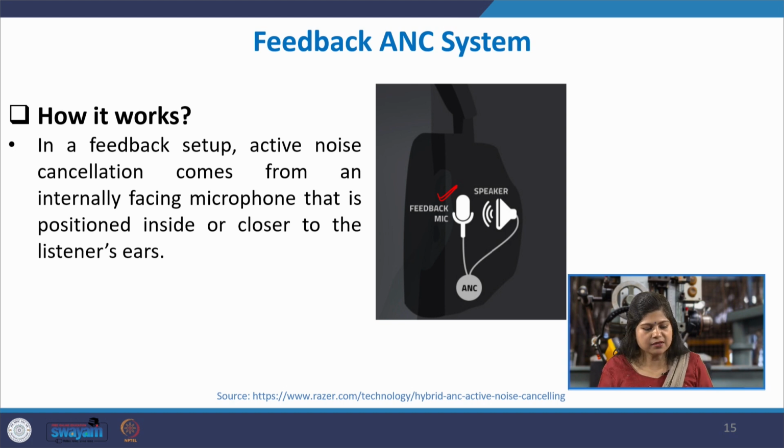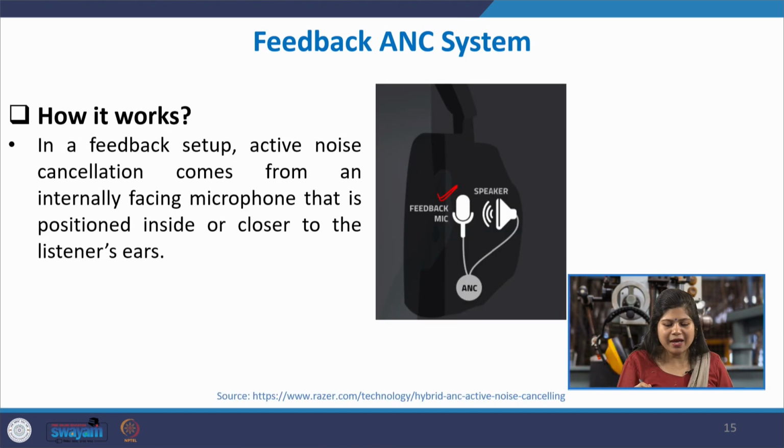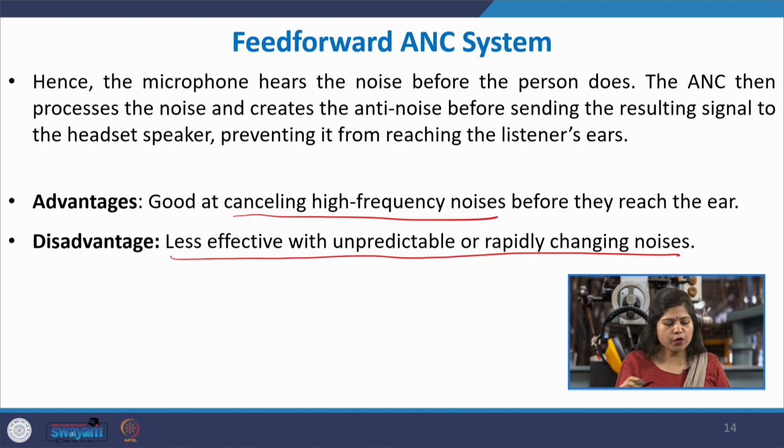So, what happens is the noise approaches and sort of reaches the listener, and the microphone just next to the ear detects it and then it drives the DSP mechanism to create the anti-noise. And due to this, in the feed forward, suppose it is a very dynamic environment with a lot of structural elements and a lot of unpredictability in the sound wave variation, perfect cancellation may not always be achieved,